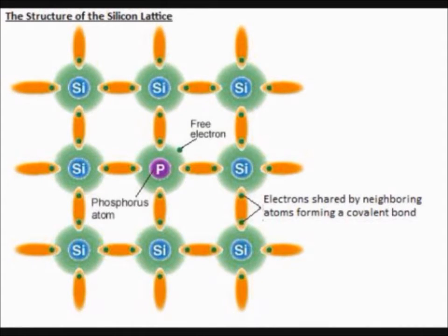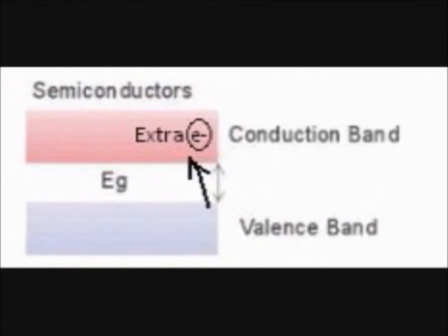Conversely, N-type semiconductors are produced by doping it with a 5 valence electron element, or group 5 element. This produces an electron in the crystal lattice that is elevated to the conduction band. The dopant has hence produced an electron or negative charge carrier free to move through the semiconductor without needing higher temperatures or light to excite it to a higher energy band.